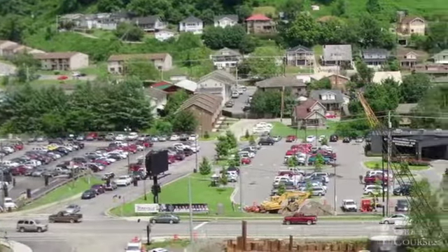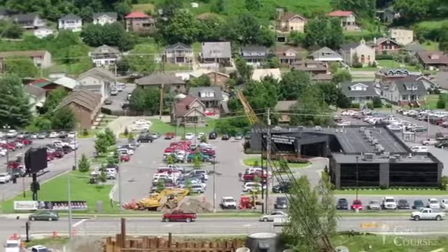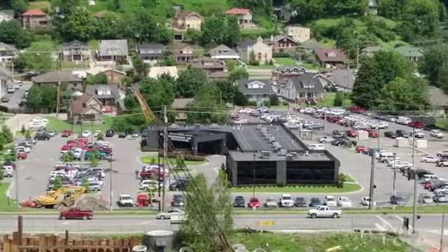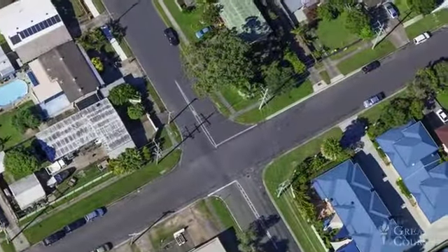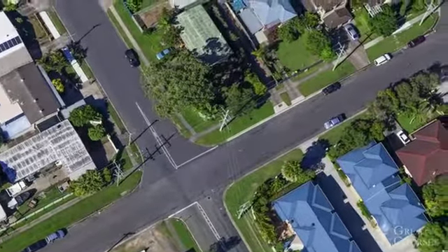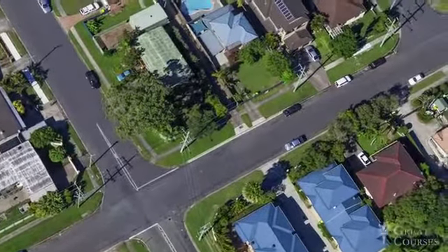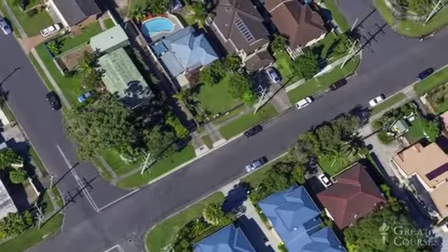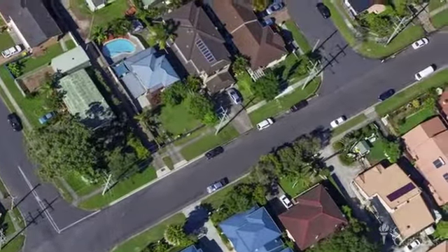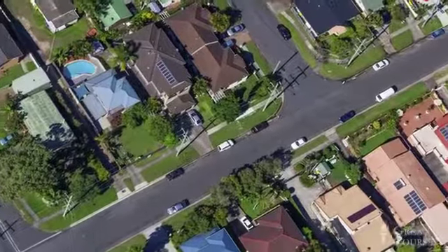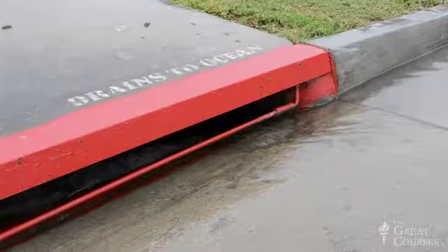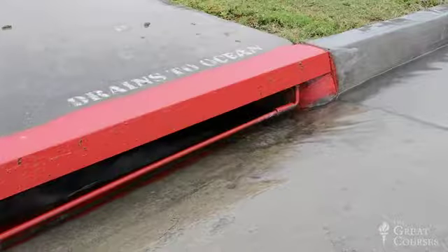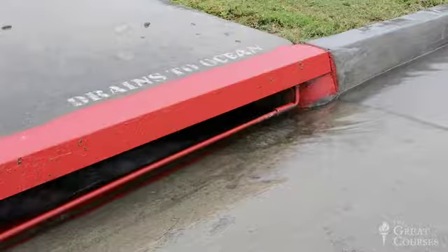Furthermore, anytime land is developed, large areas of porous ground are covered over with impervious pavements and rooftops. In this photo, look at how much of the land area that was once open ground is now covered with impervious materials. As a result, significantly less precipitation infiltrates down into the soil, and significantly more flows over driveways and streets. This increased surface flow can cause flooding, inundation of municipal storm sewers, and the depletion of groundwater, which might be used for local water supply.